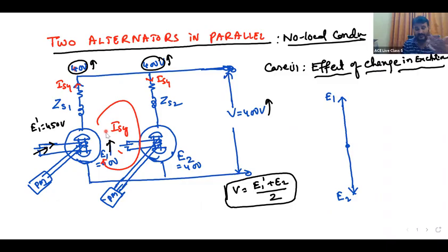And what will reactive power do? Reactive power will produce the flux, and active power will produce the torque. Well-known thing, no? As this is reactive power, this current will produce flux in the opposite direction in the first machine. It demagnetizes the first machine, and for the second machine the flux is adding, magnetizing.